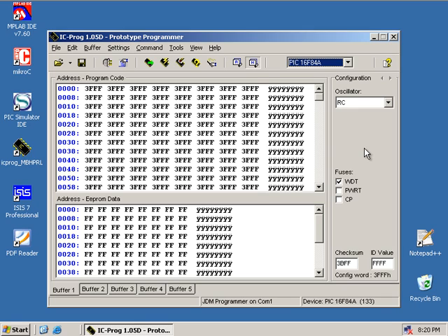After you create your programmer, you can connect your microcontroller to the computer through the serial port, and then you can use this software to program or insert the compiled version of your program to the microcontroller. And here also you have to select the microcontroller, and some of the other configurations are here. We will talk about these things when we are implementing our first project. And these buttons are for our programming task.